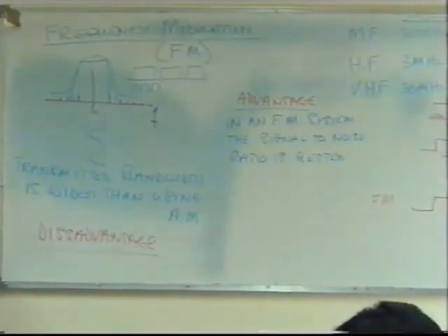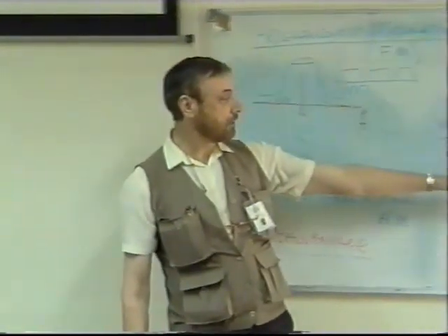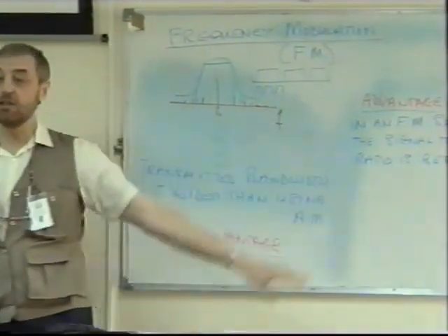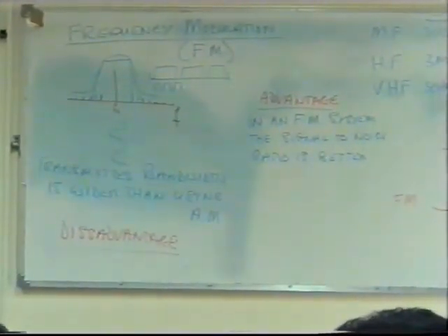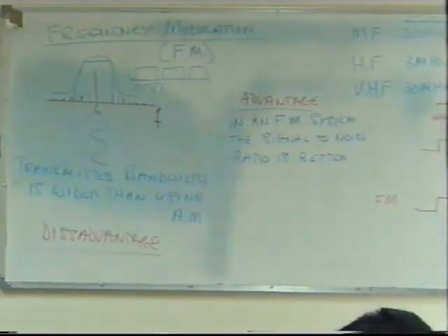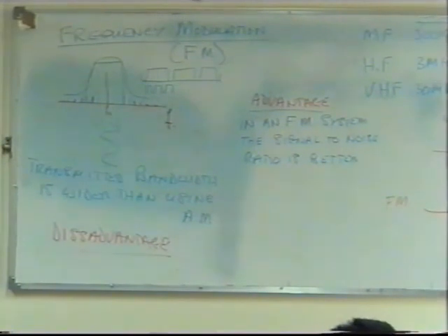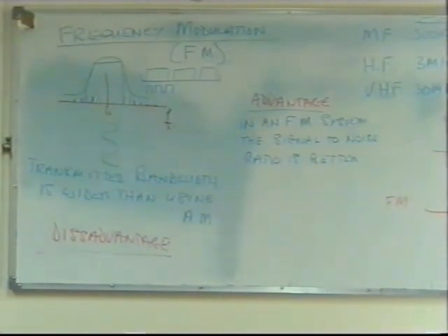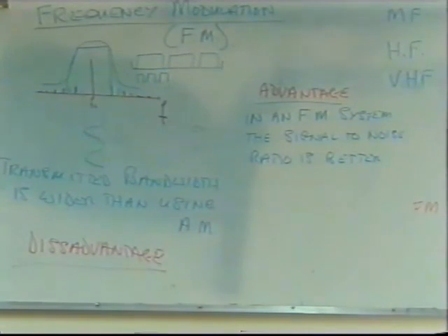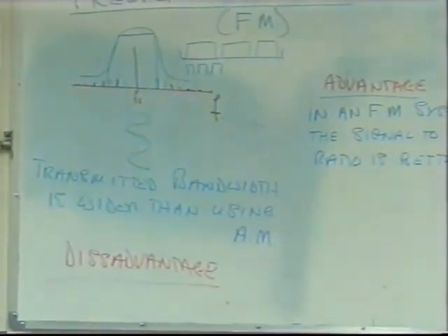There's no noise, but that's not a problem. The reason why there's no noise is because it's frequency modulation instead of amplitude modulation. In the receiver, it ignores the amplitude and just looks at the shape of the signal. A special detector is used just to detect these frequency changes, and that's what produces the output signal, say from the speaker. Different frequencies make a high bandwidth. Yes, with frequency modulation, you're using a wider bandwidth for each channel.